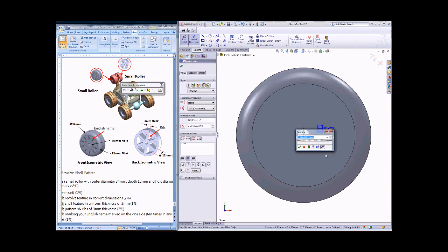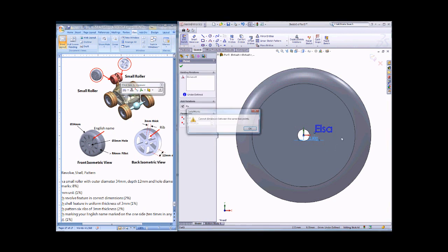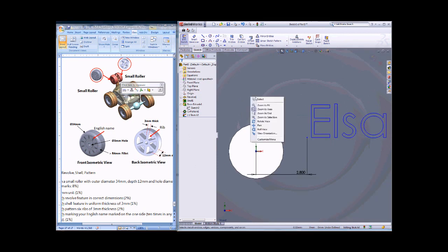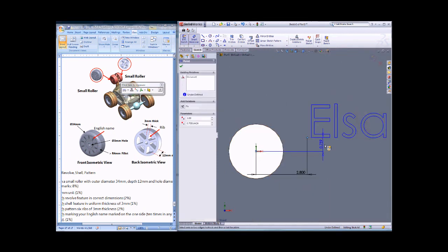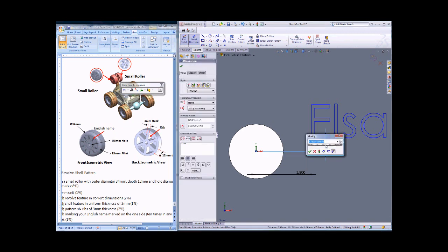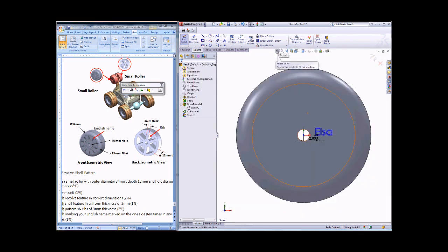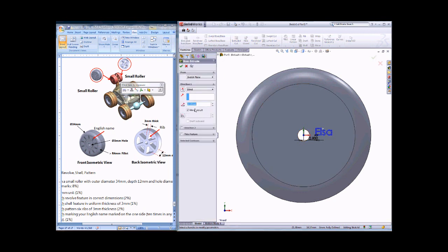And then the location, I think you can make the smart dimension in between that point. That point may be 2.8mm, or you have got that one, the smart dimension, because you need to zoom it. The smart dimension, that one to that point, you can have the 0. So you have got the name, and then using the extrude 1mm